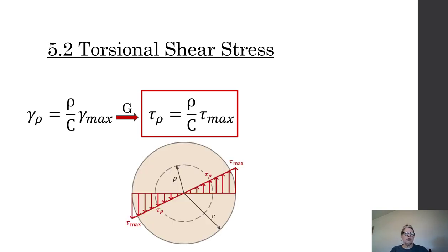relationship. So here's what it would look like sketched out on a cross section. We've gone from shear strain, and how we have that twist longitudinally and on the radius, and we figured out that relationship between our radius and shear strain. Now we've said, we figured out the strain, and material properties give us stress.